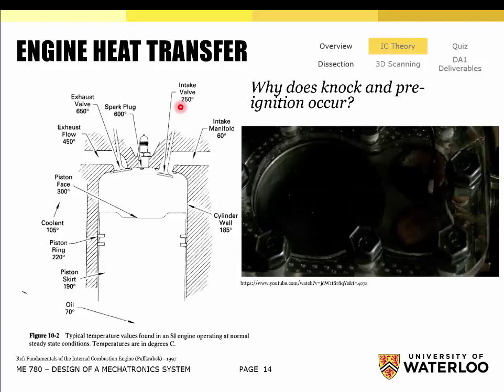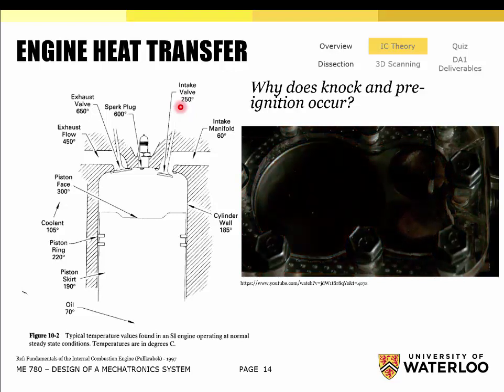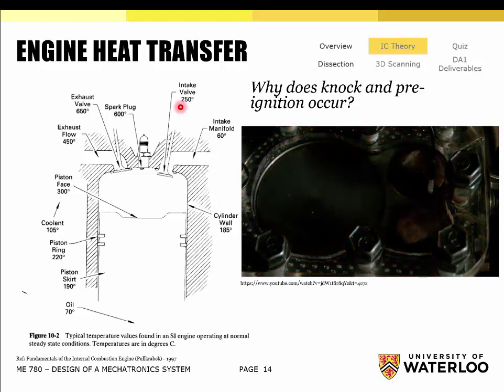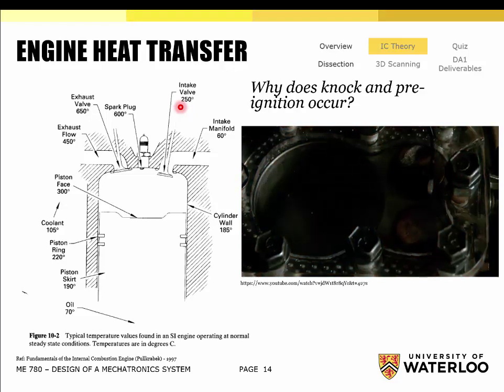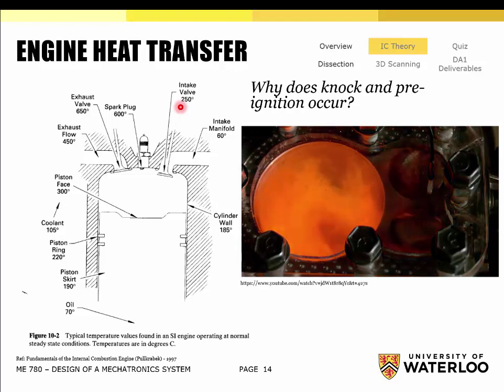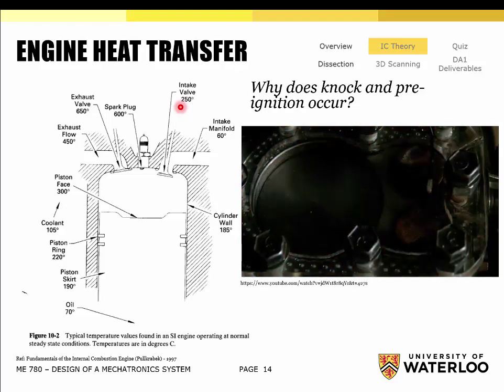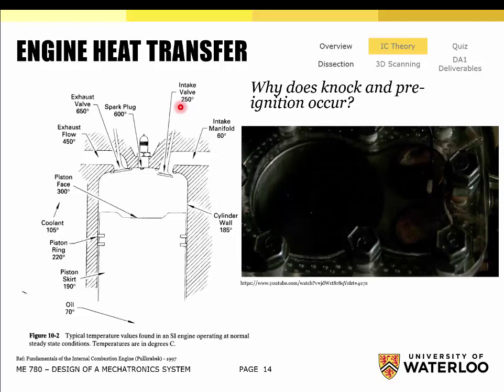Instead, you just spray the fuel into the cylinder, and you can cool off everything in the cylinder if you want, which provides a real benefit in terms of performance and emissions and efficiency. So that's why they're the wave of the future, and they're almost on, I don't know, 50 to 60% of modern vehicles, I would say, have direct injection, because you can cool the cylinder directly. We don't really care about cooling the intake manifold. That's not that important.